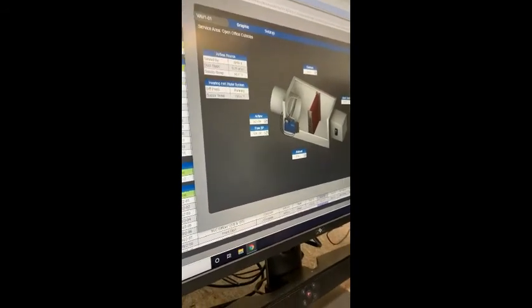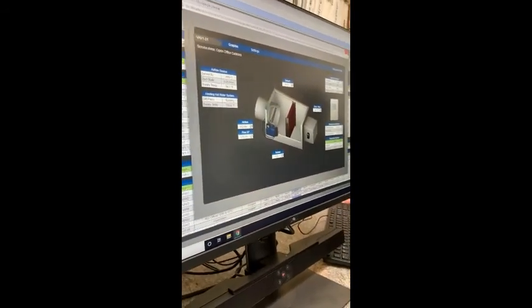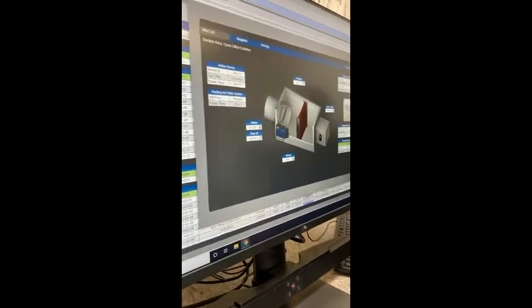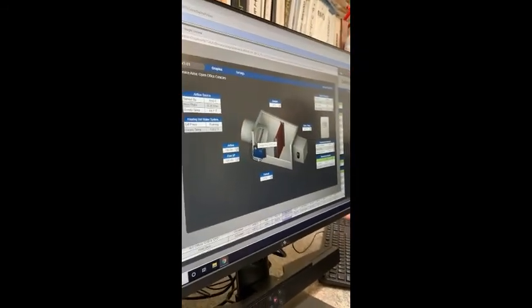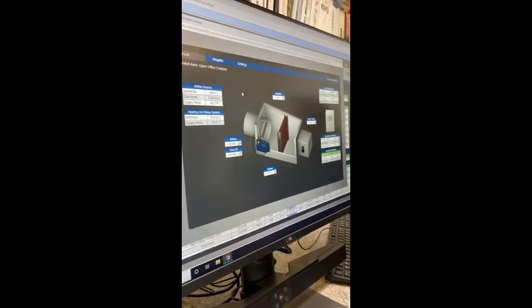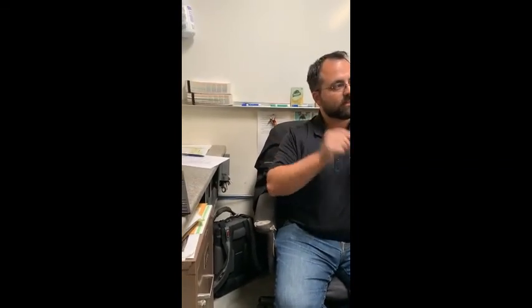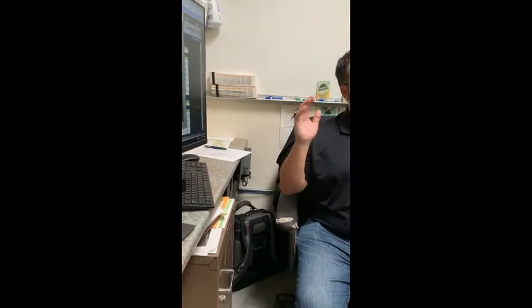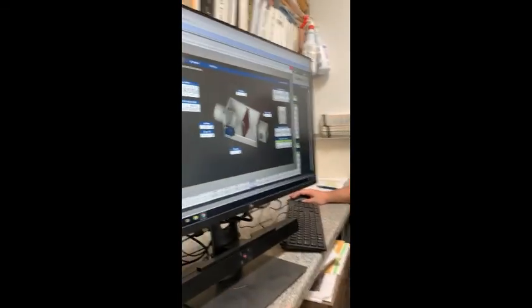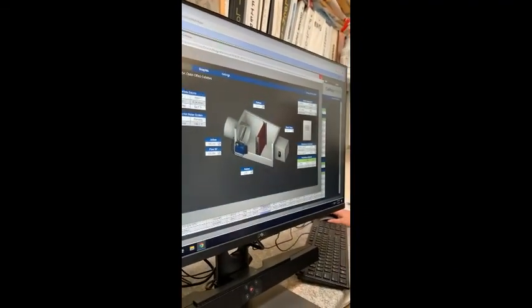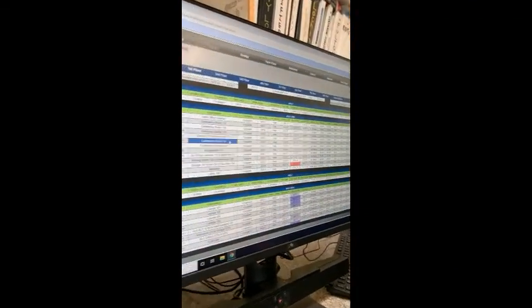Is there a static, or not static pressure, but is there some sort of something that's measuring flow inside of each one of those VAVs? Yeah, so each VAV controller has its own flow sensor. Okay. Basically it's a differential pressure sensor that looks at the downstream pressure versus upstream pressure, and it uses the box size and what they call a K factor to determine basically what the flow is by those values. And we'll go more detailed into the VAV boxes as well.